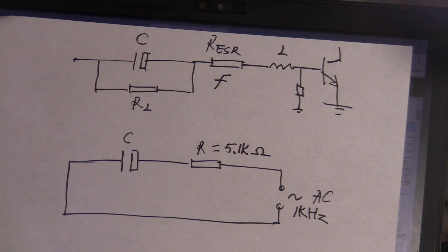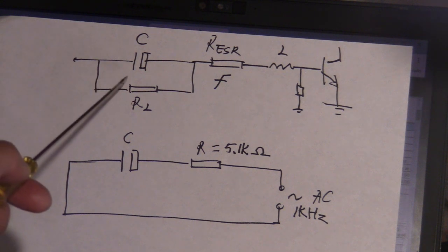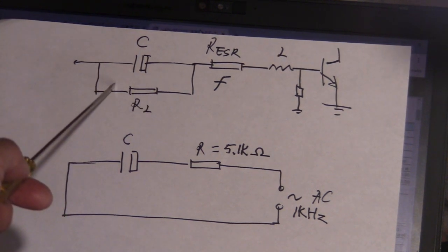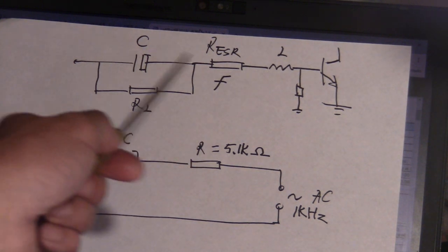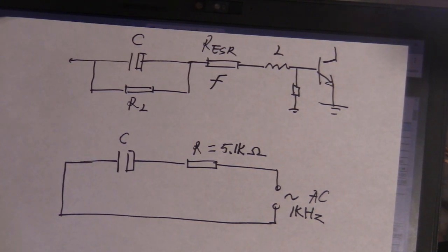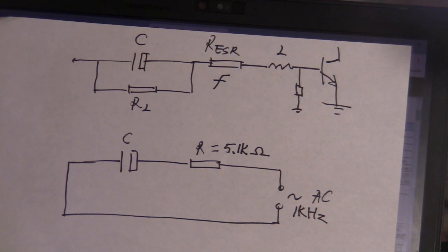There are many old amplifiers that have a phono input, connected to the turntable. That section has a very small signal input. So in that area, any capacitor in the signal path has to have very little leakage, very good frequency response and very good temperature stability, to be able to work in a good amplifier.